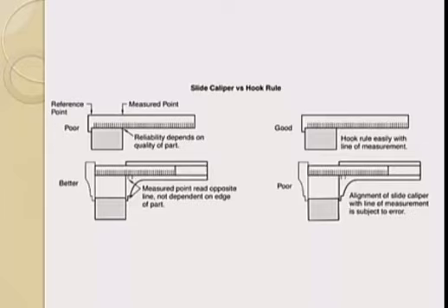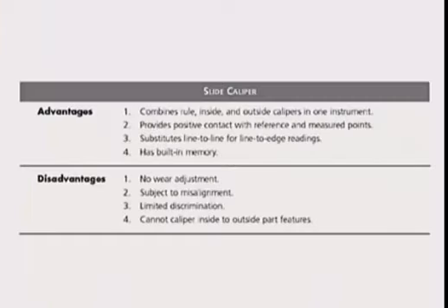It's still important, however, that when you're using a caliper the scale is in line with the measurement. If it's out of alignment, you will have error. Advantages of the slide caliper: it combines the rule, inside and outside calipers into one instrument.